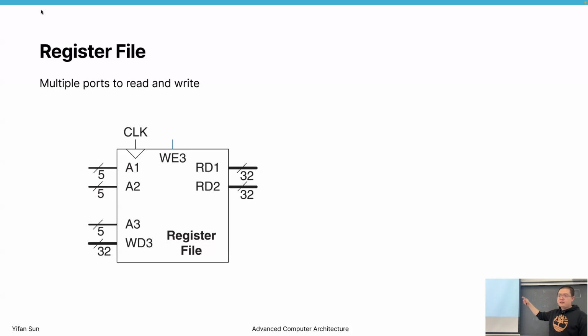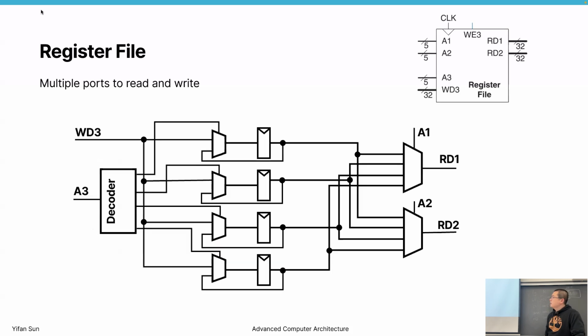In that case, it's better to design the register file with 2 write ports. Okay, so this is how the instruction set may determine the microarchitecture design. Although, even if you have this type of design, can you support a 2 in, 2 out architecture? Yes, it's just a performance issue, right? There are always high-end chips and low-end chips, and some cost lower energy but take longer to execute. It's always a trade-off.